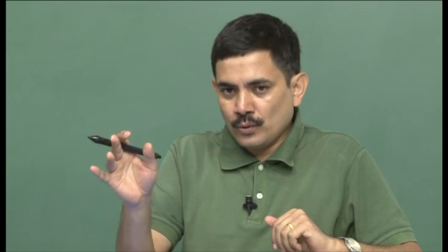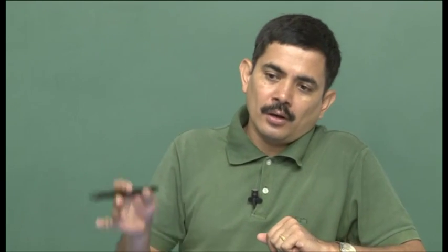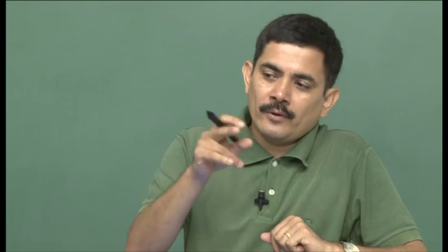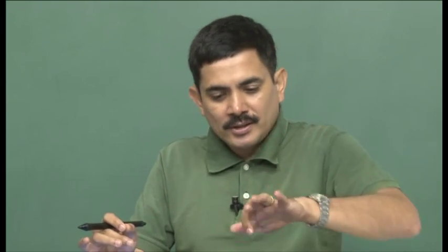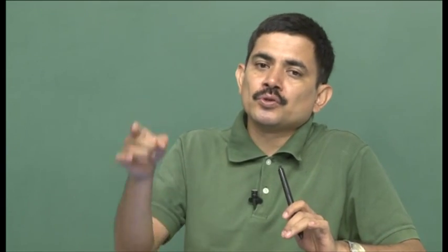This is the pairing question. What should I pair, U1 Y1 and U2 Y2, or Y1 U2 and Y2 U1? Until now I have been assuming the pairing is fixed. But now the question is, in a multivariable system you also have the choice to choose the pairing.